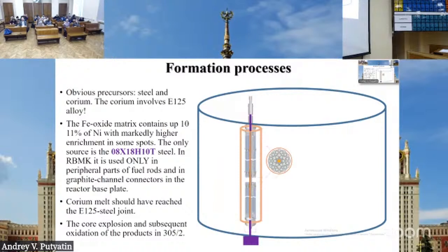And then when you have two pellets in solid contact, they start to expand in the radial direction, and they start to interact with the cladding, and they can blow up the cladding. And second, you have a prescribed place for volatile elements. Of course, this central void will form anyway, but you can have a kind of preferential site for volatiles. So both thermomechanics and, let's say, chemistry.